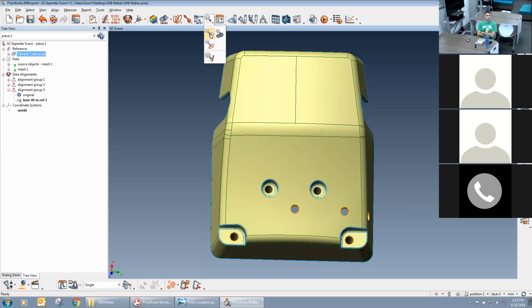So that would be a simulator, for instance, if the two side locators were just a pin that was perpendicular to the A datum that you press the part against, you would use those rather than it being a pad or a cone tip point that you're pressing against.